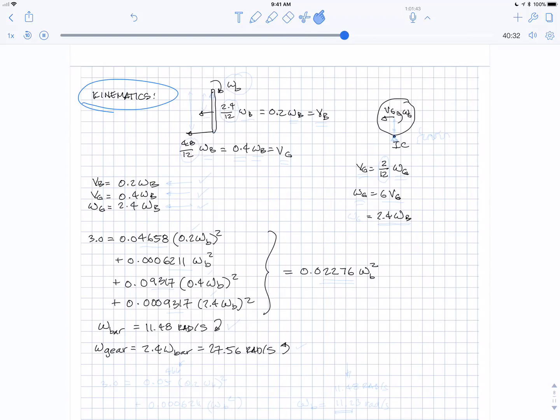Okay, so we know this bar is definitely spinning about this point here because it's pinned. You look at that picture, there's a gigantic pin right here at A. The gear is definitely spinning about the bottom because it's got teeth. That's how gears work. They make gears so they don't slip. So it's definitely 0 velocity right there. Okay, so knowing that, here's omega of the bar.